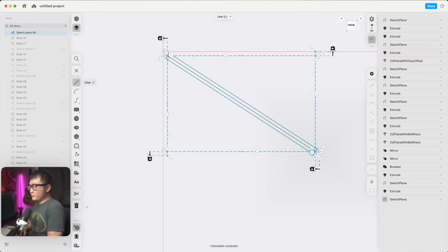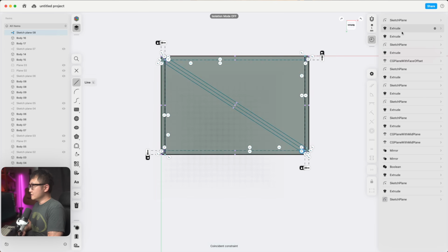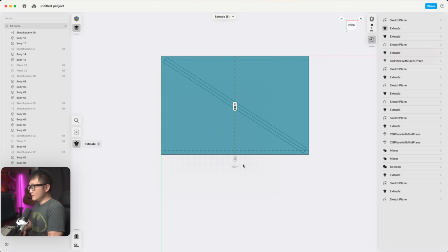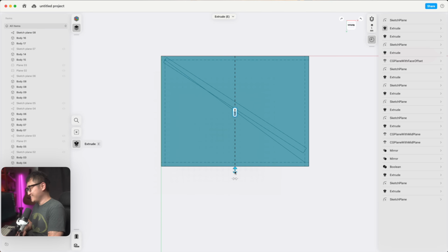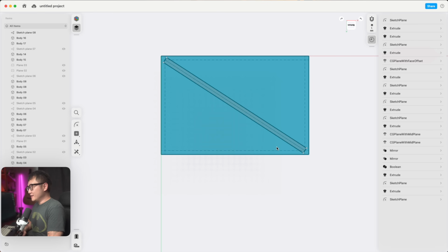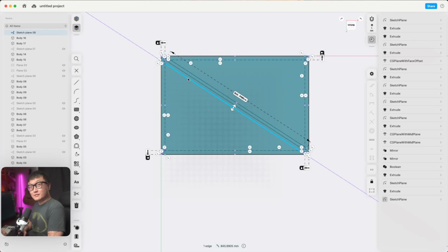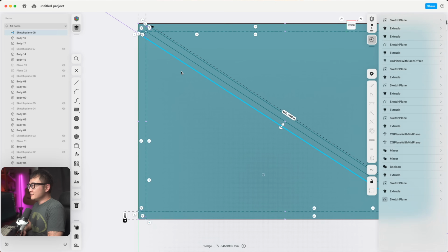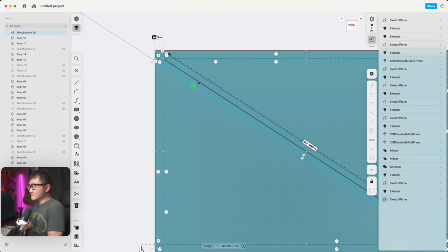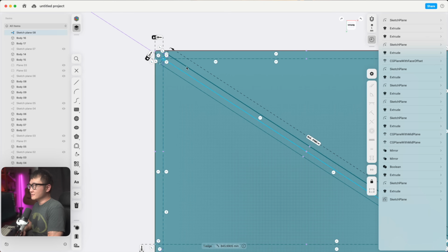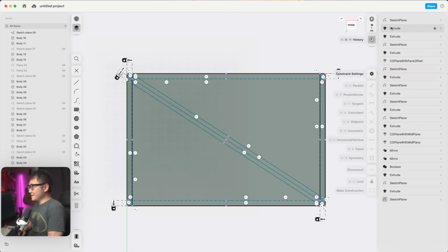So now if we bring everything back, and let's select the second extrusion, if we change this, everything, nope, that's not what it's doing. You know what, I totally forgot that when we use this offset edge tool, we still need to manually come in here and select these lines and lock the dimension down to 15 millimeters. Completely forgot that I need to do that. All right, now let's try that again.